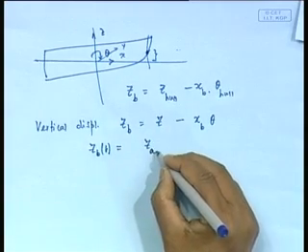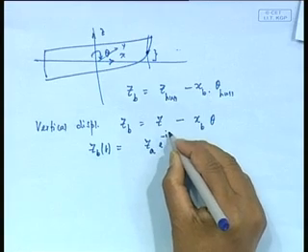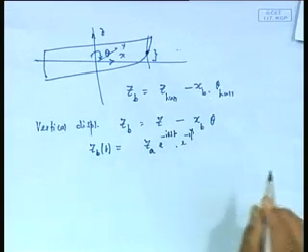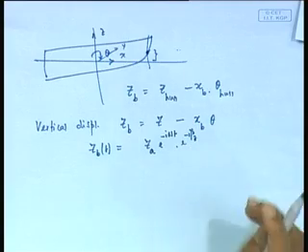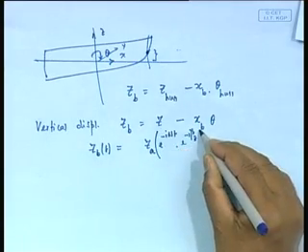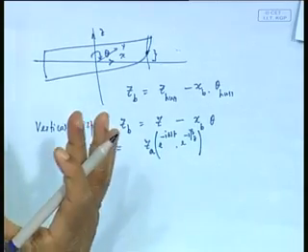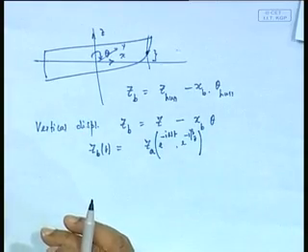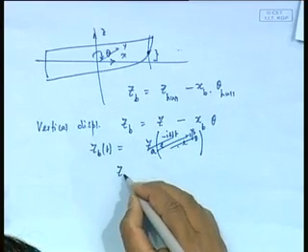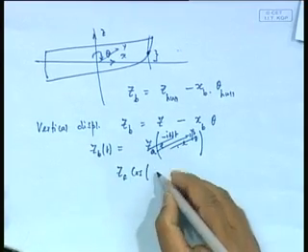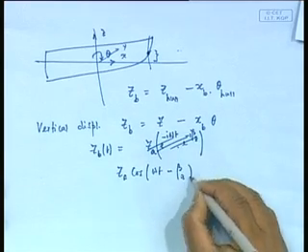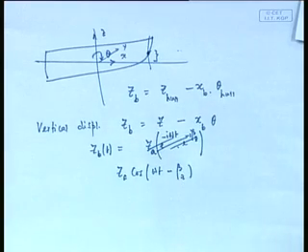Z is the amplitude of heave into e to the power of minus i omega t, maybe e to the power of minus i beta, beta of heave Z. Essentially it is a sinusoidal function, the real part of that, or if you do not like it, let me put it this way: it is basically Z_A cos of (omega t minus beta_Z), plus or minus.